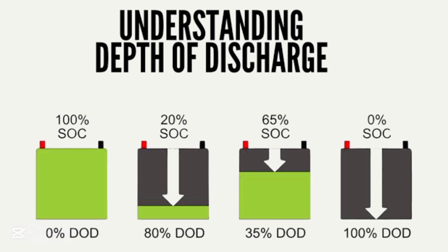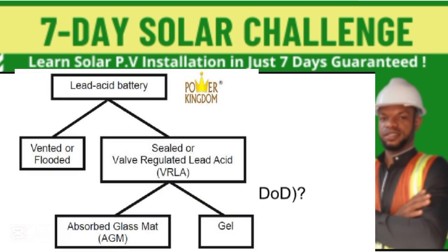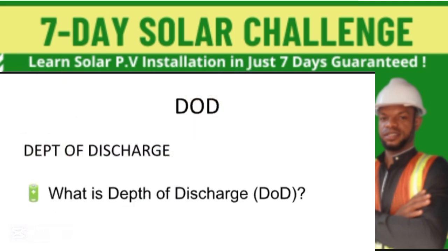What this simply means is this, like I've explained before, batteries, when fully charged, most of them cannot give you everything they have. Do you understand that? We explained that lead acid batteries, both the flooded lead acid battery, sealed lead acid battery, and their variation, which is AGM and gel batteries, some of them can only give you 50% of the charges they receive.